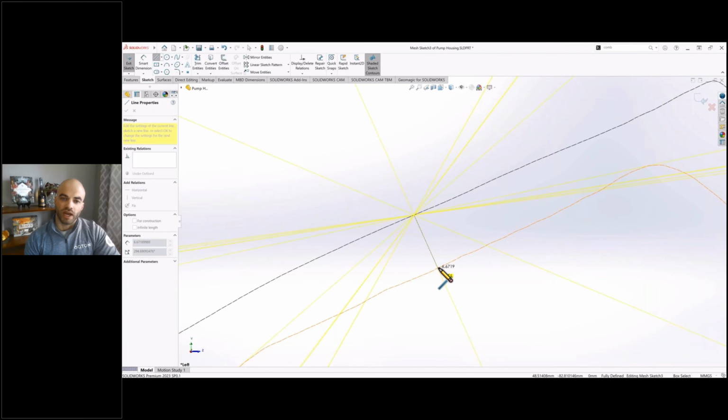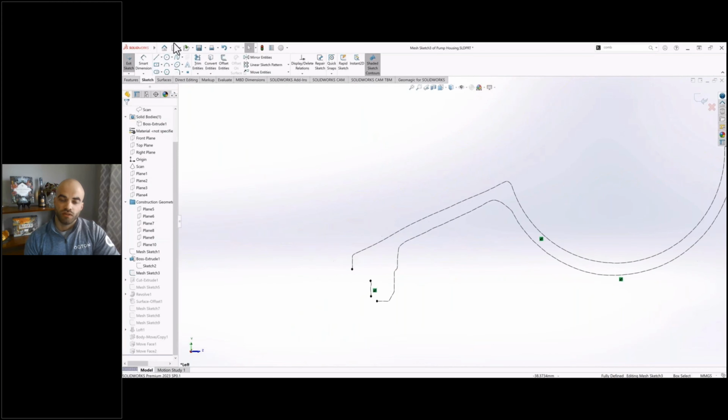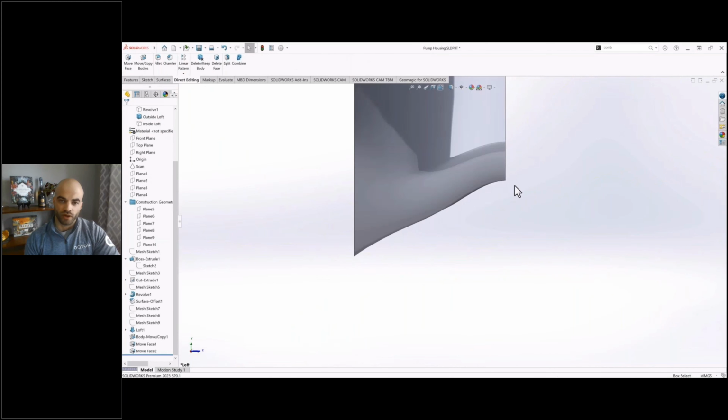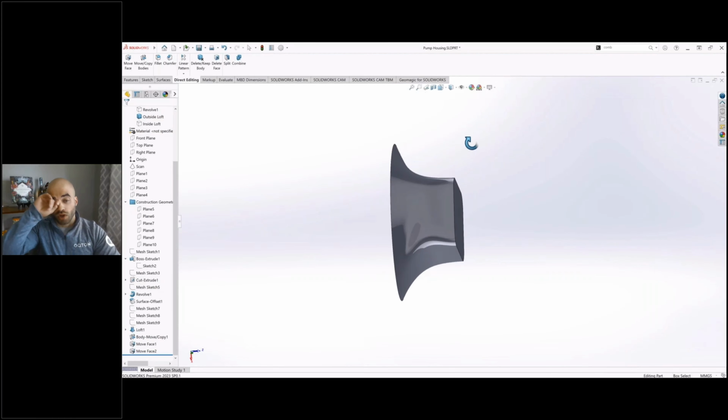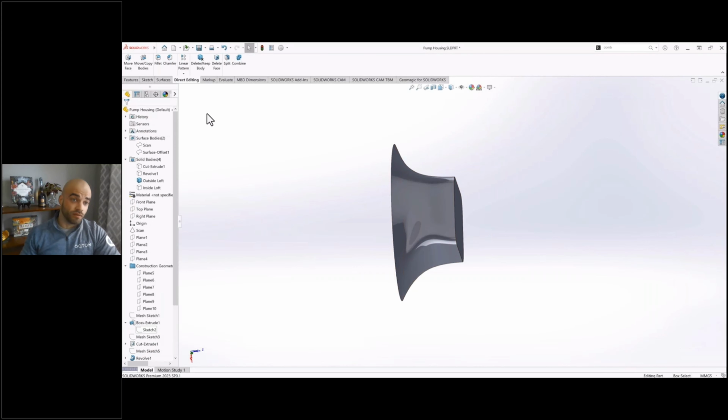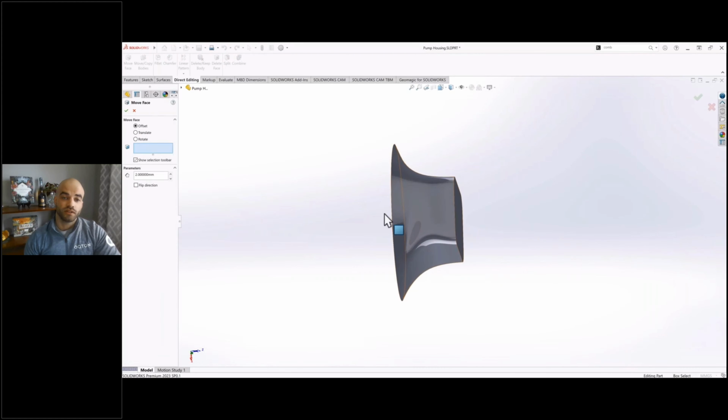So what I'm working on now is checking this offset for the outer surface, which, if you saw there, was just a rough measurement of like 6.75, I think it was. So I'm going to call that 7. So that's going to be my offset, as I've created a copy of that inside loft. And always good to use naming conventions to make sure you keep things straight. So I call them inside loft, outside loft, to make sure I'm not offsetting the wrong one.